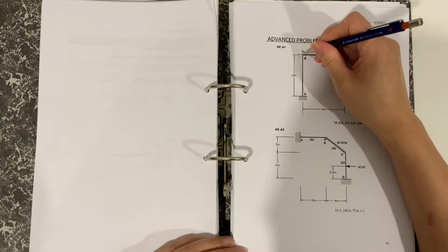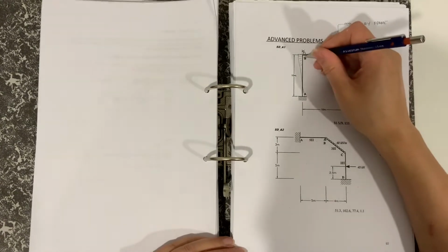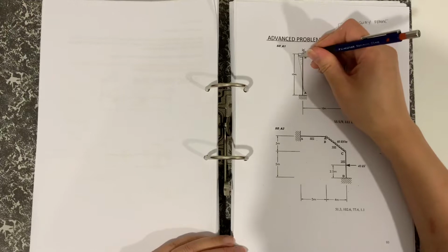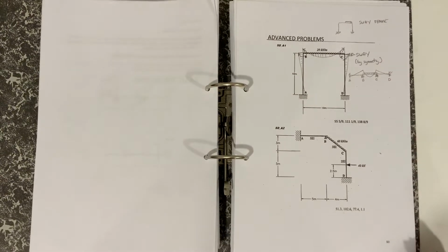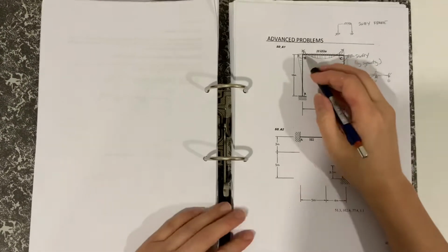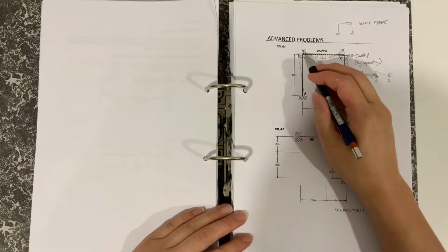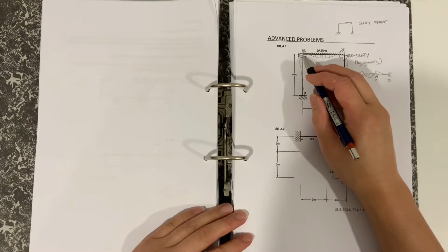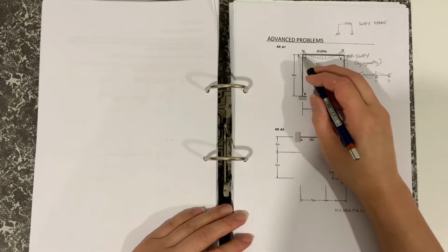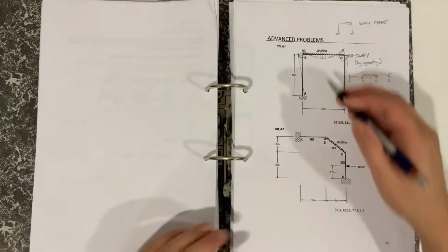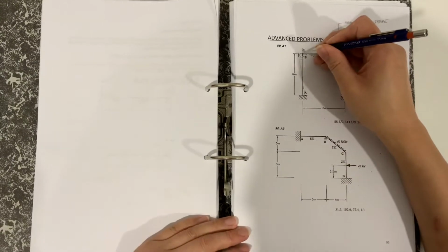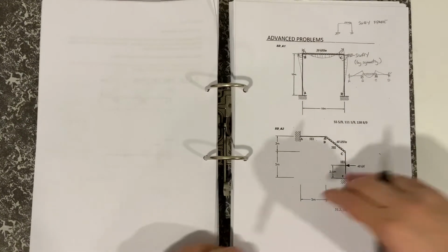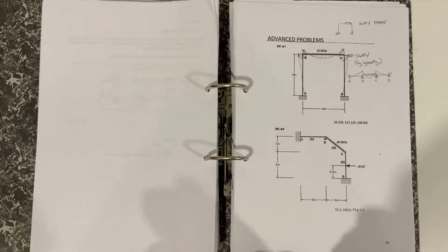At the end of the calculation, you would deduce that that arrow is in that direction. So as we said, this is on the outside, so the bending moment can't switch. So the outside would put that as the tension side, and so on the column side, that also has to be the tension side. So the tension sides cannot switch without an external moment being applied.